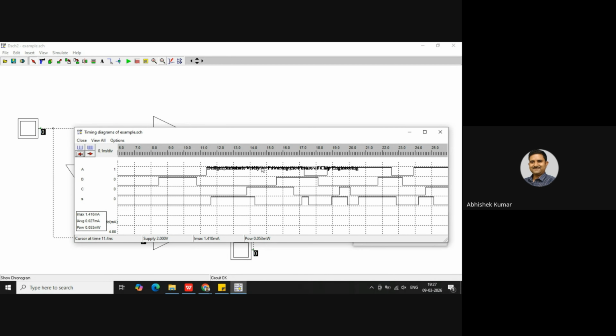Next combination 1 0 1. Here I have got output 0. Now 1 1 1, output is 0. 1 1 0, for a very small time it makes one combination and the output is 1, because after that the input changes to 0 1 0 and the output is 0. So in the same way the inputs appear, I will get the simulated waveform.